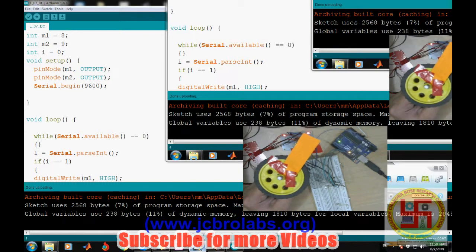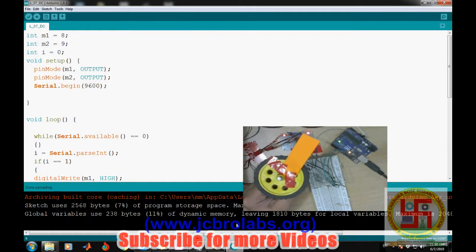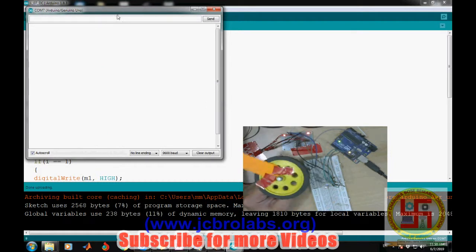Now the motor is stopped. So we'll open the serial port. Now if we send 1 and press enter, it has started rotating in one direction. Now if I press 2, it will change the direction.